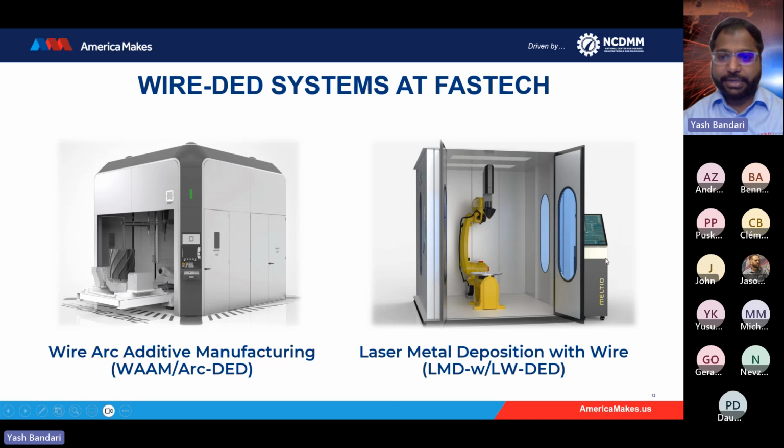And then on the LMD wire side, we have a system coming from Aditech Meltio, where we use robotics, and it can also print up to 1 meter long components, but in fact 1.8 meter long components. Most of the components that we get from customers are about 200 mil to 800 mil. But there's a lot of room that can be printed in these systems.